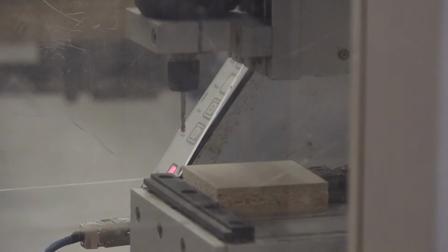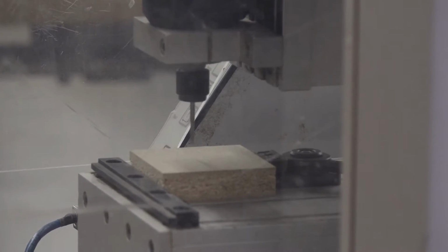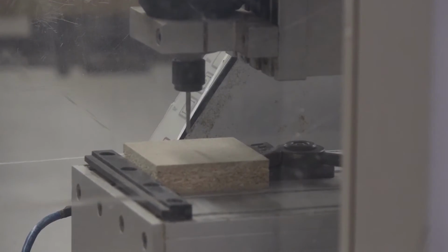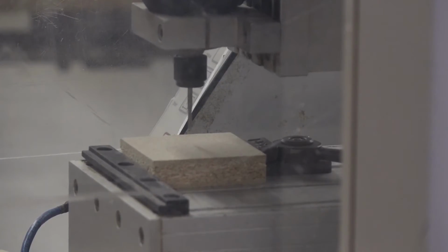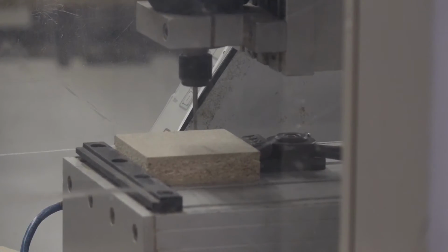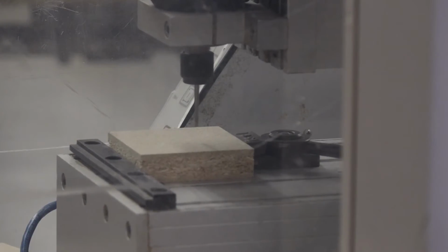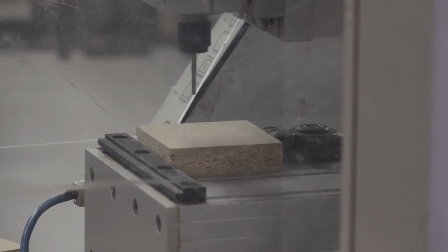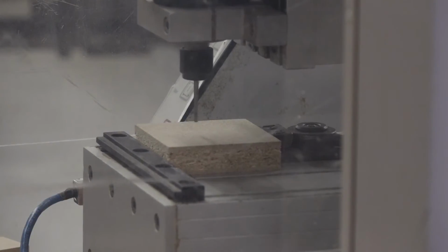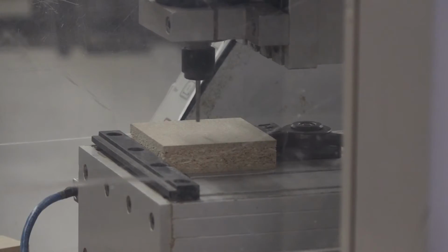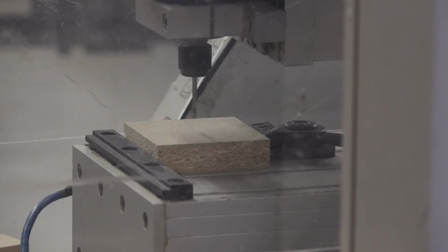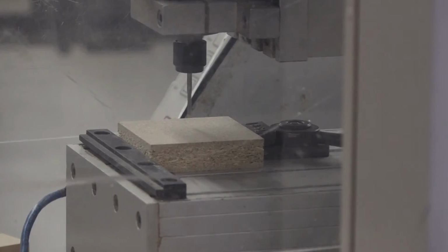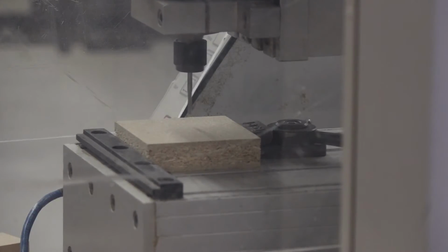It'll count down, and then it'll start milling. And you're just watching to make sure that it's going to do what it's supposed to. If we had started it flush with the wood, it would be cutting right now, but I raised it up. This won't take very long, so I think I'll just go ahead and have it complete. But if you had a big project, maybe you'd only do the first pass just to make sure it's looking good and it looks like it'll fit in the wood. Then we're going to stop it. We're going to move it back to the origin by hand, manually, get it set to 0, and then we'll cut it.